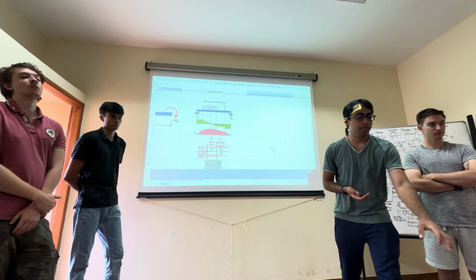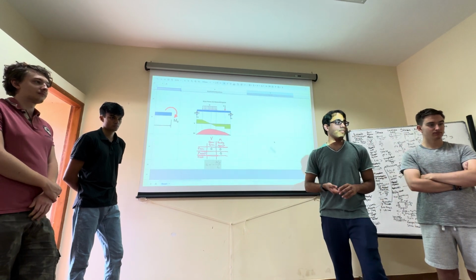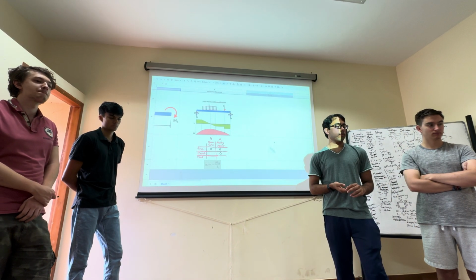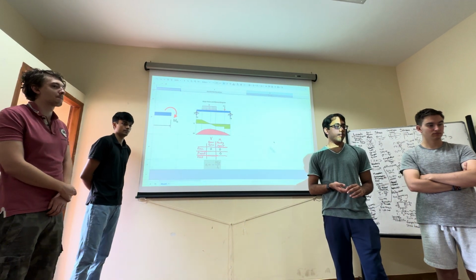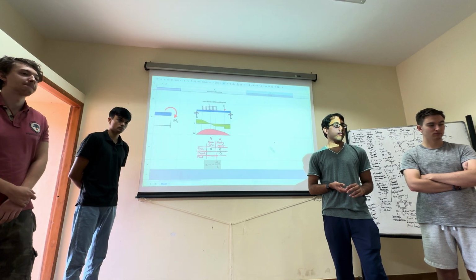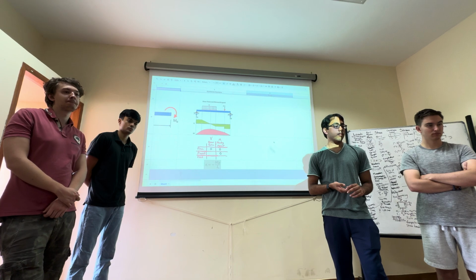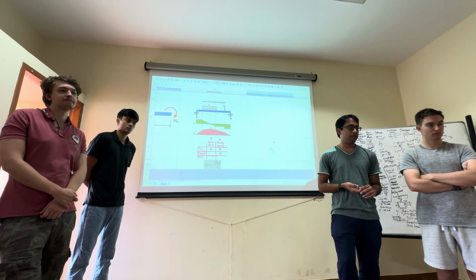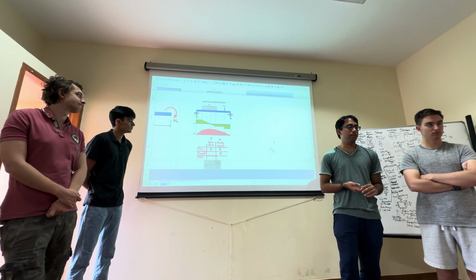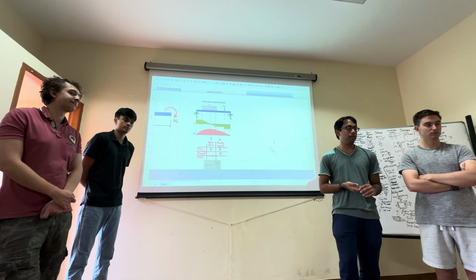On the other hand, the displacement is also 0 because it cannot move beyond that pin where it is pinned. So you could have some mixed kind of boundary condition, and pinned is a classic example of that. Whereas a fixed end, both the conditions are geometric boundary conditions.